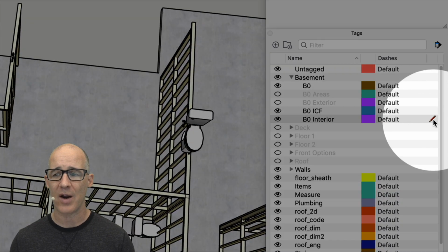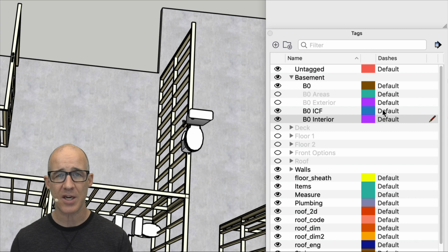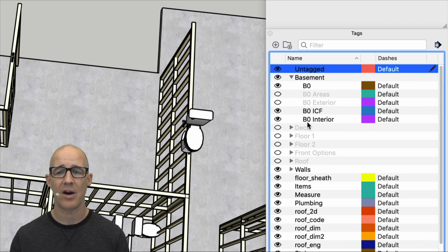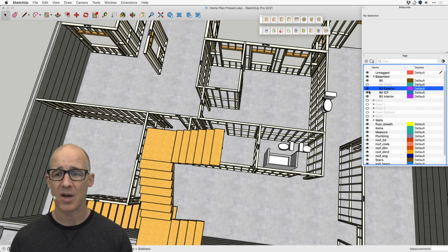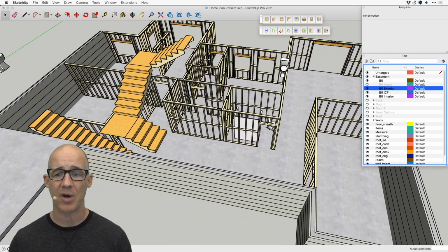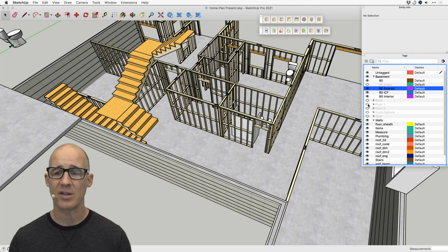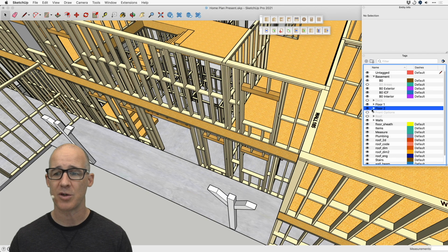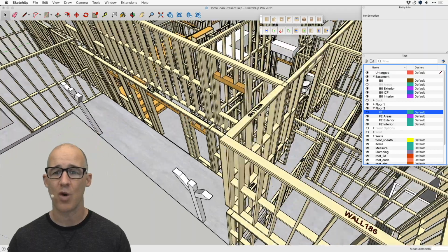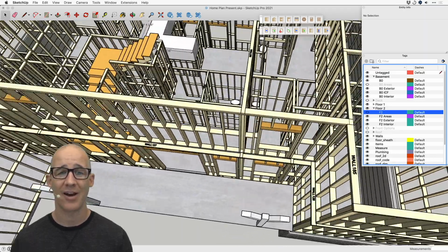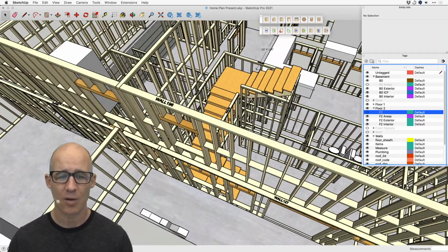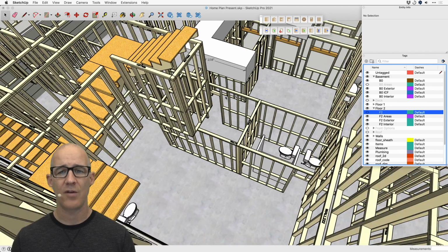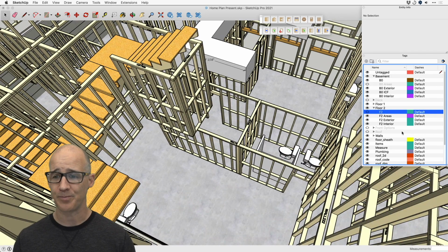Make sure you select the right layer that you want to be editing, click Regen, and then just go ahead, select off of the layer, and then go ahead and determine whether it's actually going to work by turning on and off those walls, which becomes very important when we're working, because obviously I want to be able to, if I need to adjust my basement, work on my basement without seeing all of my other floors and geometry and everything else that gets in the way. Of course, if you want to work like this, looking through all of your layers of floors and working that way, great.